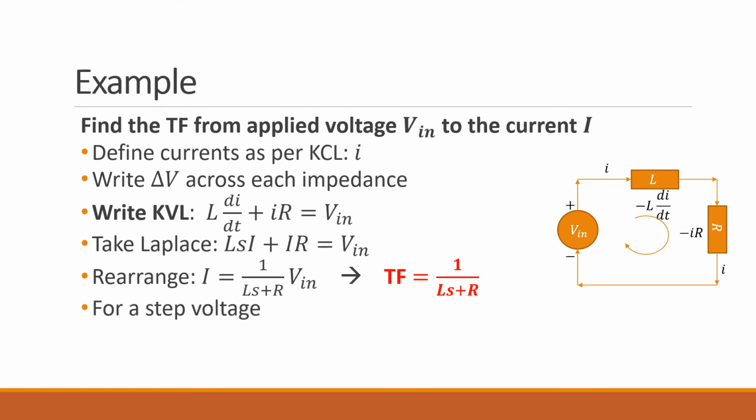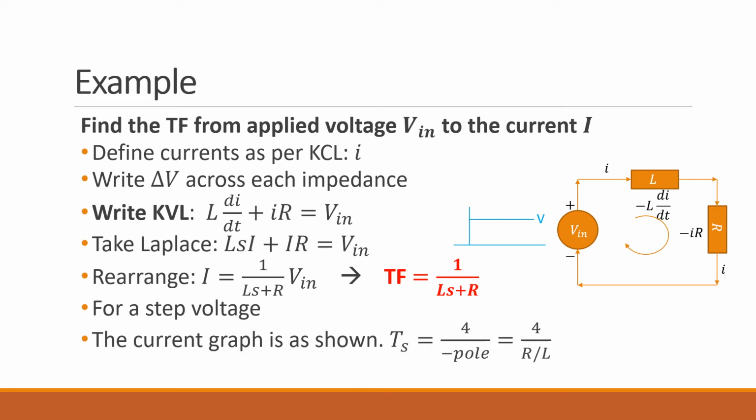Note, this is a first order differential equation and a first order transfer function. Hence, if you gave a step value of the voltage as shown, the current graph will be as shown here.